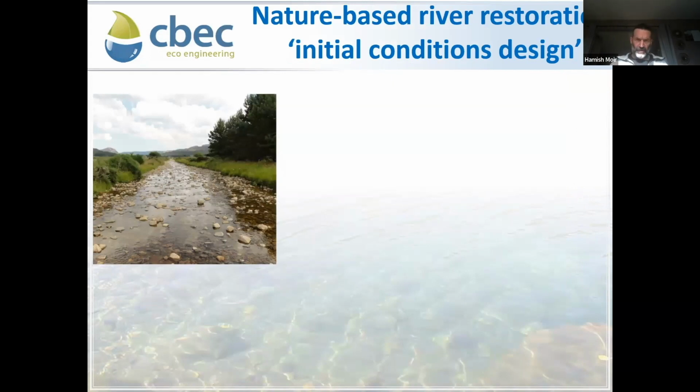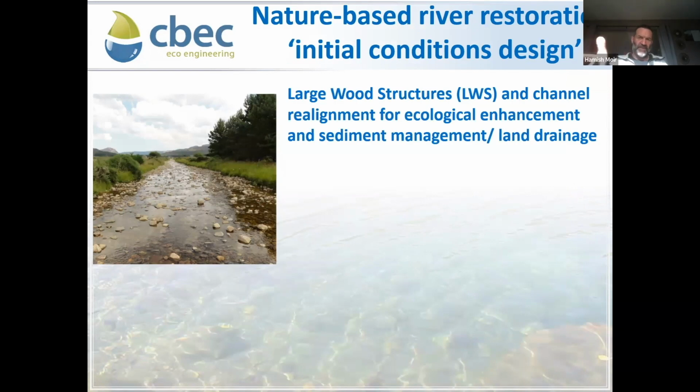So the design approach was to implement large wood structures in combination with channel realignment for these benefits, mainly ecological, but also in a practical sense for sediment management and land drainage issues relating to agriculture. This is where the constraints come in. We have to consider these issues as well.